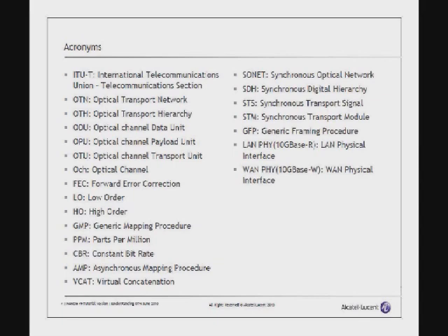Some key elements of OTN: the Optical Transport Network is the overarching standard that ITU has come up with, looking at trying to put more intelligence, and we'll go into some detail about that, into the optical layer of the network. And then OTH is the hierarchy that's underneath the OTN, and then ODU, OPU, and OTU are various units, and I've got some slides that talk about how the hierarchy is built up.